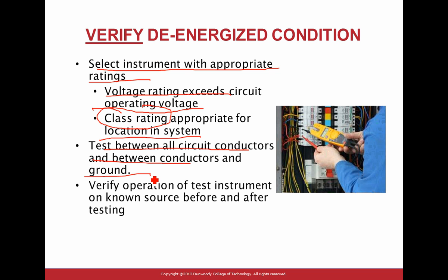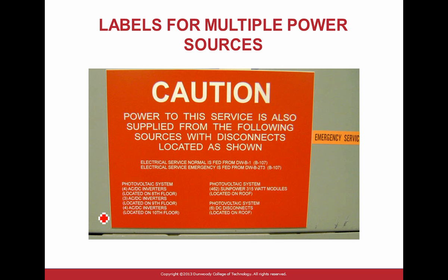By the way, while you're verifying, you're dressed up, because until you verify the absence of voltage, the piece of equipment must be treated as energized. And until you verify it. We talked about the instruments, unknown sources of power. Any comments, guys, about using the instruments?